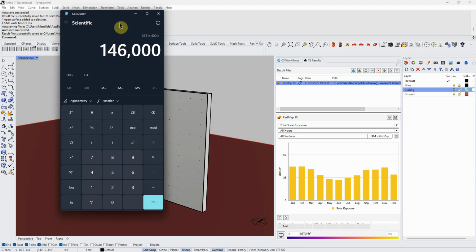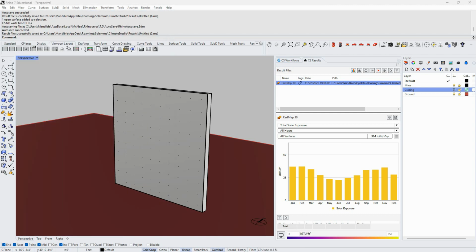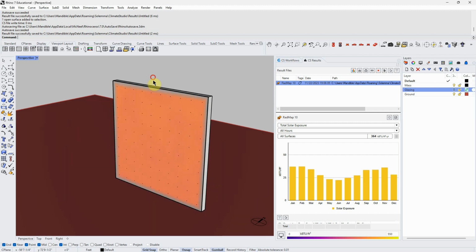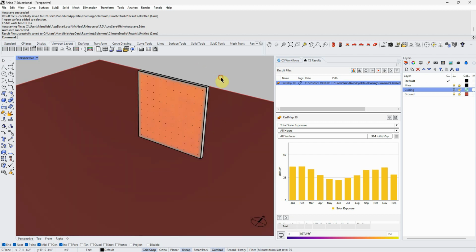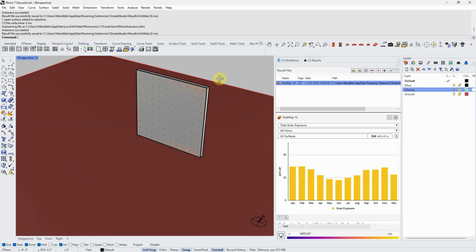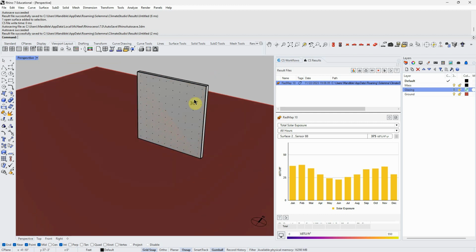It's 145,000 kilobtu's, so 1,000 BTUs. It's not a trivial amount, even something this small. So then, the next thing, but that's not really going to work, because if we said my concrete wall is getting 365 kilobtu's per square foot per year into the space, that's not accurate, because that's just what's hitting the wall.